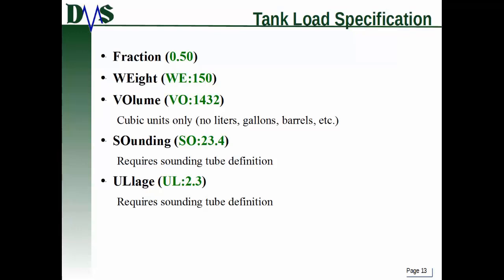Now there's another way to do that. Still use the sounding tube, and you can specify an ullage. An ullage is the distance from the surface of the liquid to the top of the tank. So sounding is going from bottom up, ullage is going from top down.